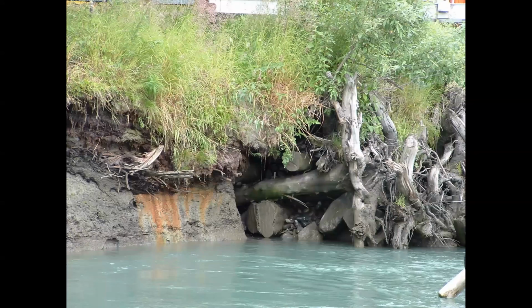I like to bring this slide in. This is again a Kenai River slide. One thing to consider is that anytime you're doing any sort of toe protection or revegetation, you need to think about your tie-in points. In this case, this root wad was just kind of left hanging. They didn't have a really good tie-in point, they just stopped the project. They probably should have continued the project a little further downriver, maybe talking with their neighbors to see if they could continue downriver, or tying in another technique if they needed to.